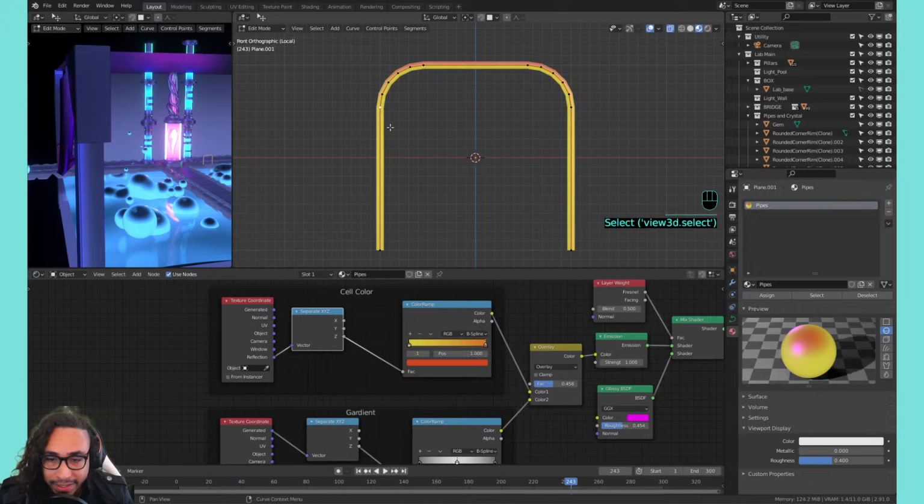All right, so let's do something here. I'm experimenting, I'm going to select this line here and put a point in the middle by selecting the top vertice, bottom vertice, and hitting right click and subdividing. So that puts that point in the middle. I'll do the same here. And then I'll select these two middle points and hit F. And it cannot make a segment. Okay, okay. So undo.